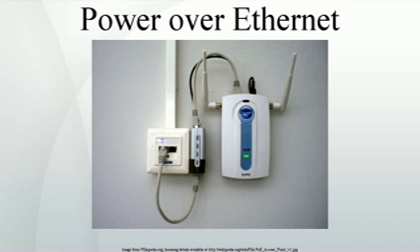Non-standard implementations. Cisco. Cisco manufactured WLAN access points and IP phones many years before there was an IEEE standard for delivering PoE. Cisco's original PoE implementation is not software upgradable to the IEEE 802.3 standard. Cisco's original PoE equipment was capable of delivering up to 10 W per port.